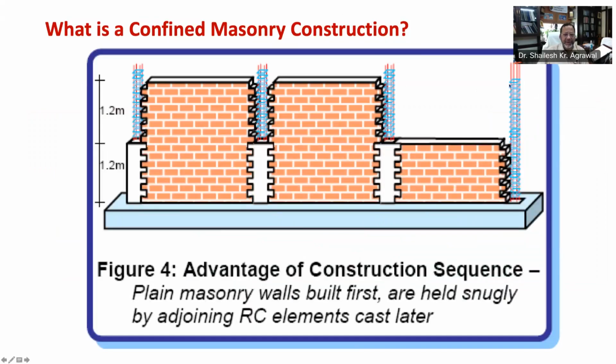RCC confining elements enhance the stability and strength of brittle masonry walls, that is, interaction between masonry walls, structural integrity, and containment of earthquake damage within masonry walls. These advantages lead to ductile earthquake performance of confined masonry houses over those of alternative concrete and masonry building technologies with a relatively lower level of technical effort.